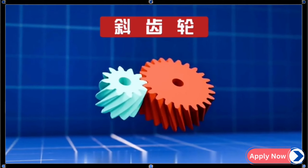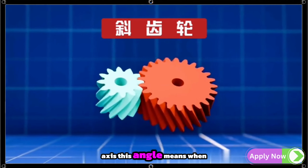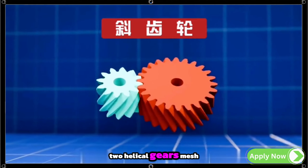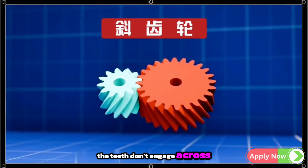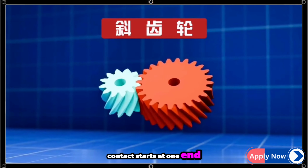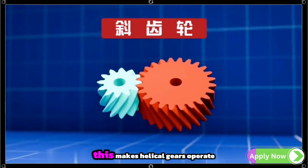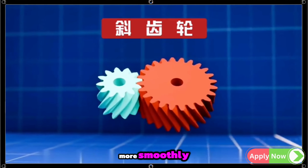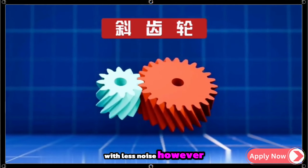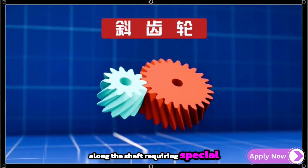Helical gears are similar to spur gears, but their teeth are cut at an angle to the rotation axis. This angle means, when two helical gears mesh, the teeth don't engage across the entire width simultaneously. Instead, contact starts at one end, then progresses across the entire tooth face. Compared to spur gears, this makes helical gears operate more smoothly, with less noise. However, helical teeth also generate axial thrust along the shaft, requiring special bearings to handle it.